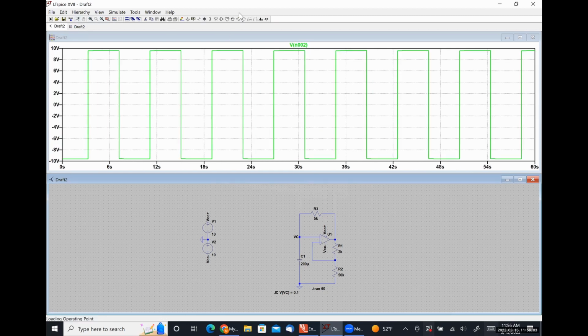All right. So we have oscillations. The whole purpose of this thing is to just generate oscillations. There is no input signal whatsoever. In a real system, we wouldn't have to say, oh, there's a little bit of voltage on the capacitor, because thermal noise would eventually drive this thing into oscillations. The random fluctuation of electrons in the capacitor would eventually be enough to start the oscillations. And once they start, they don't stop until we turn the power off.